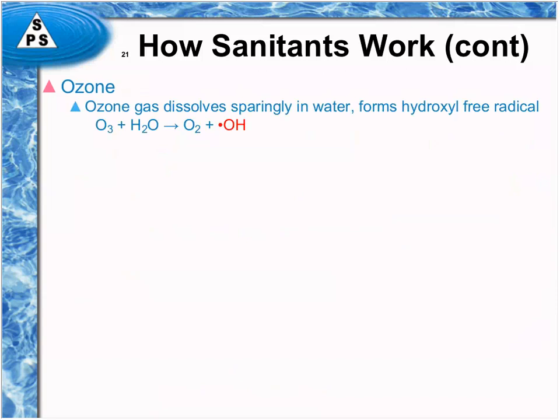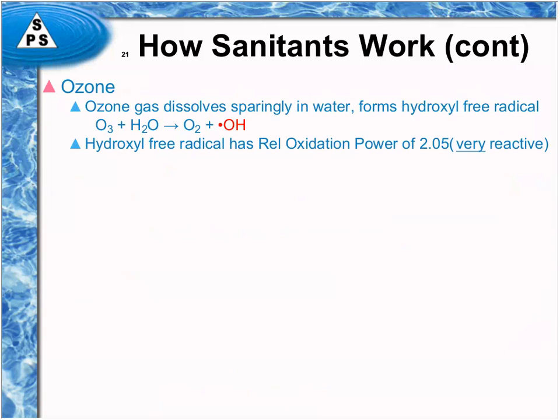Ozone. It's becoming more and more commonly used. The ozone gas dissolves sparingly in water, but as it interacts with the water, it releases a hydroxyl free radical. Now, the hydroxyl free radical has a relative oxidation power of 2.05, and that is very, very reactive. In fact, it survives only for nanoseconds once it forms. So it interacts with the first thing it encounters. It's so reactive. It doesn't last, like I say, but for nanoseconds.